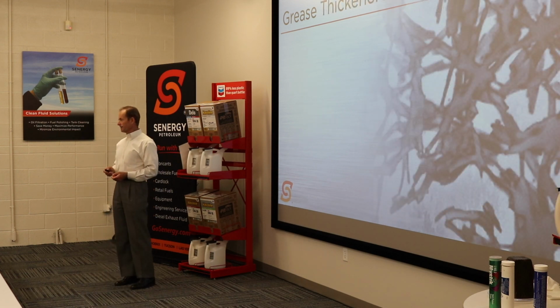Yes, Joe, who can't wait until the questions part of this. I was just going to ask really quick, what does oxidation look like in a grease? Joe is asking what oxidation looks like in a grease when it happens. You get a combination of darkening and the same kind of burned smells, and sometimes in conjunction, you get some drying that happens. Things tend to get dried out.